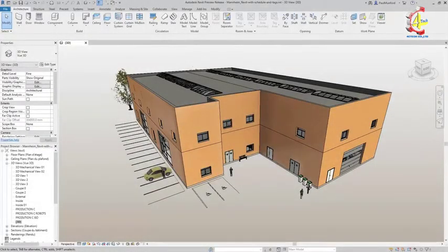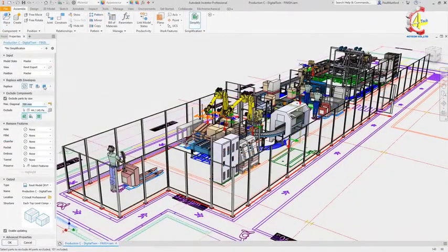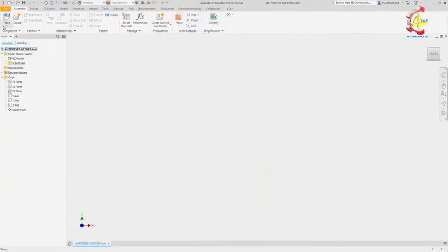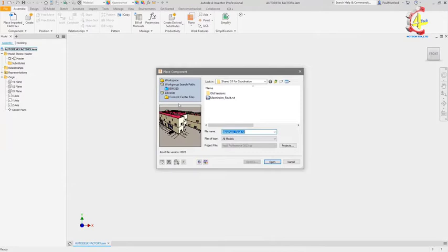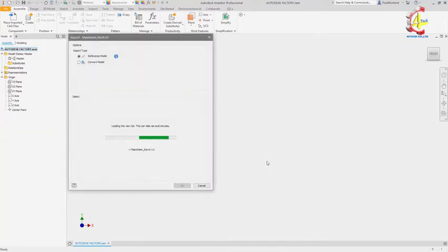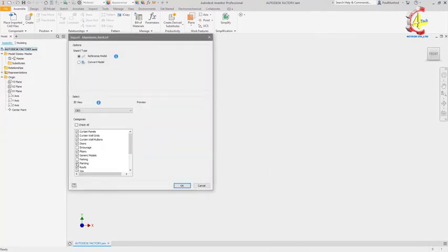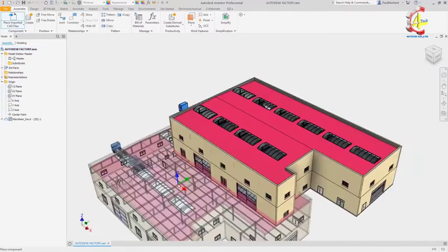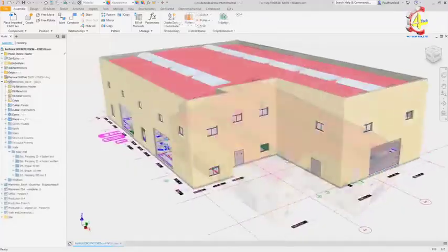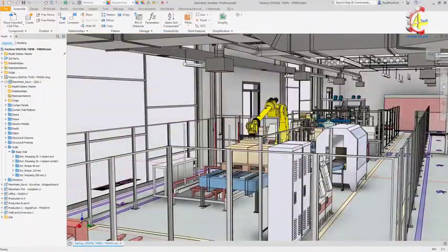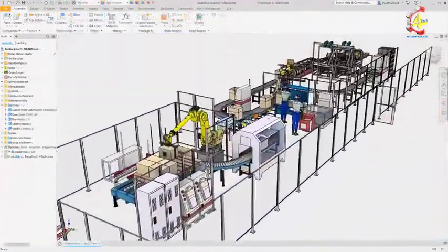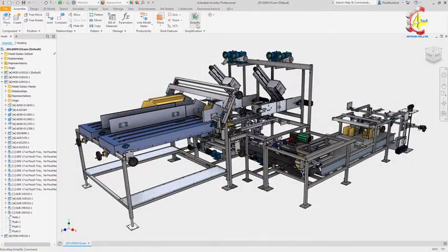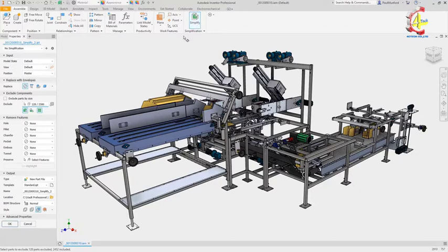Autodesk Inventor 2022 continues to improve collaboration on BIM projects with the ability to save native Revit project files from Inventor. In this example, we already linked a Revit model into Inventor via AnyCAD to use as reference while designing. Now our design is complete, we'd like to share our design with a Revit user for coordination. Before saving our Inventor assembly as a Revit model, we'd like to remove manufacturing detail from our design, which is unnecessary for coordination on our BIM project.